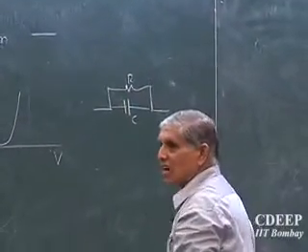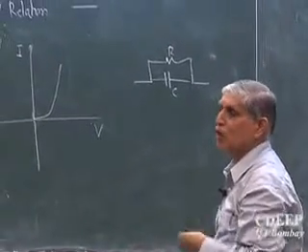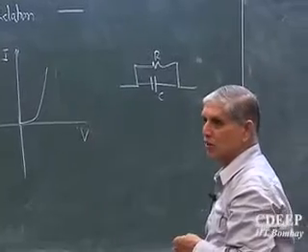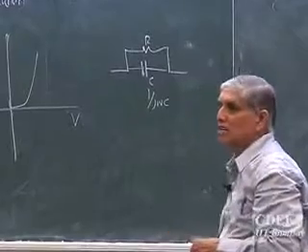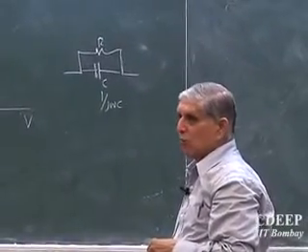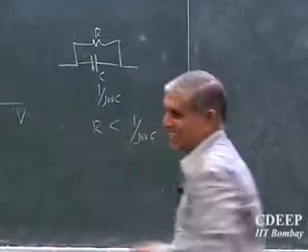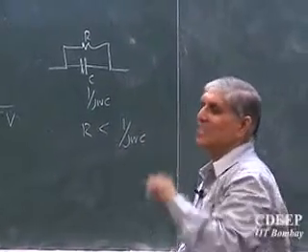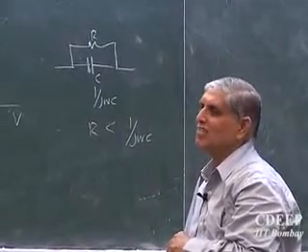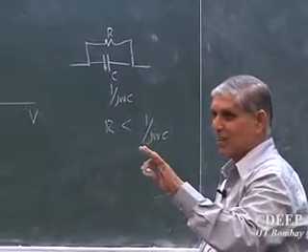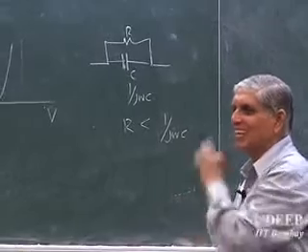In reverse bias, this R is very large, 10 to the power 6 to 10 to the power 7 ohms, tens of megohms to hundreds of megohms, depending on the saturation current. This capacitive impedance 1 upon j omega C is smaller than R. When I go into forward bias, R will be much smaller than that, because the current is essentially enhanced. So the C effect in forward bias, of course it exists, I am not denying that. But I thought first let me do IV, then show you how much R I am getting. Why I neglect the capacitance.